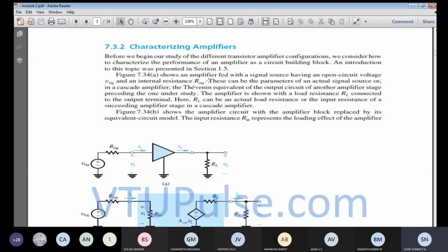The same goes for the differential amplifier. At the input stage of the operational amplifier, the differential amplifier stage will be there, where the input is given to the MOSFET or the BJT itself. So the characteristics remain the same, whether it is an operational amplifier, a BJT amplifier or a MOSFET amplifier. We are going to see the important parameters characterizing the performance of an amplifier.